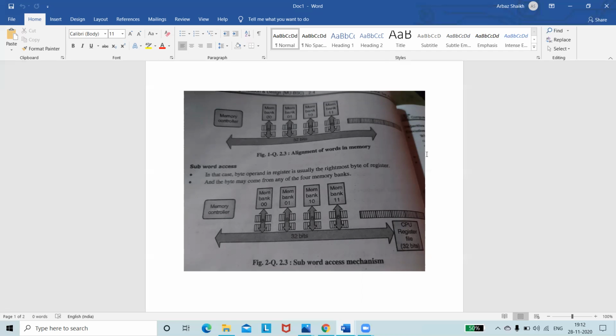According to the above discussion, the CPU accesses a 32-bit word of data starting at a byte address that is 4 times 0, 4 times 1, and so on, where the byte addresses are 0, 4, 8, in binary numbers like 0000, 0100, 1000. Unaligned access doubles the access time of a word.